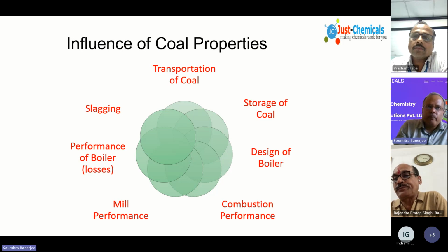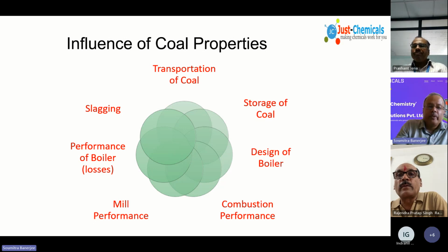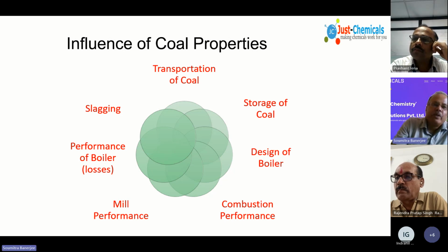Storage of coal is one of the very important things, which we will be talking about in the next session of the slides, means today only, next session of the slides. Then design of the boiler. How does it affect the design of the boiler? If the boiler is designed for a different coal and the coal you are actually getting is different, then the behavior would be different. Then combustion performance. CFBC, AFBC will have different combustion performance. Pulverized fuel boilers will have different combustion performance based on what is there in the coal. What are those properties?